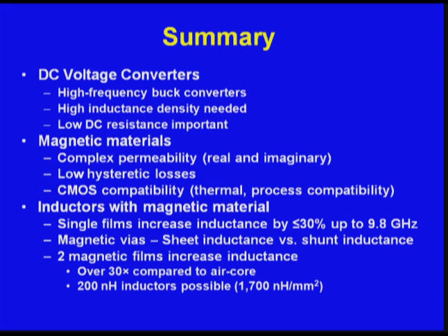Some of the papers I showed earlier don't have on-die inductors, I should point out. But what we did do was increase the frequency to see if we can do something at high frequencies. So you need to look at those papers that way. And then magnetic materials, we looked at the complex permeability, the real and the imaginary part, which creates the losses.